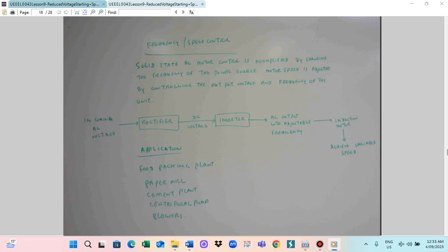So this is a triac. The triac is connected to the load here. This one will be a direct control type. The variable firing scaling is controlled by the variable resistor.